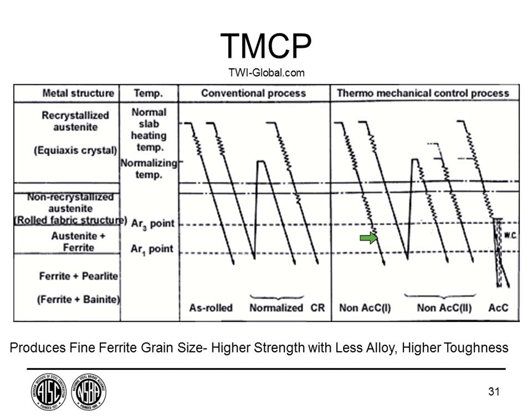Okay. Thank you. The next question is, are there issues with field welding in cold temperatures? Oh, yeah. In fact, when we get to the fabrication, we have definite preheat temperatures that the steel has to be at before we weld it. There will be some minimum temperatures, because if it's too cold, we're going to get a problem with that martensite. So there are preheat temperatures specified in the welding specification.